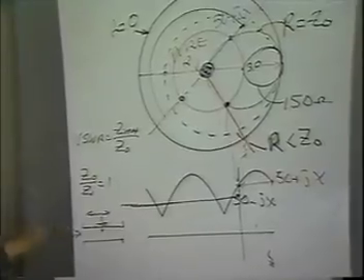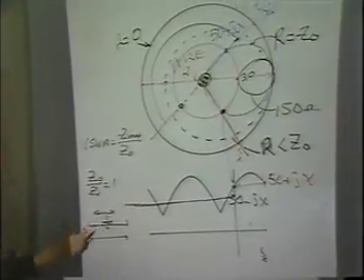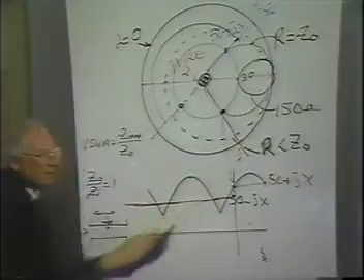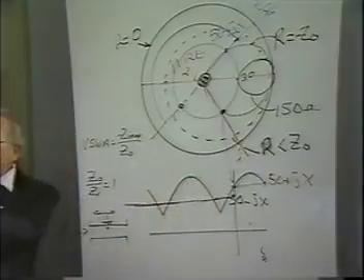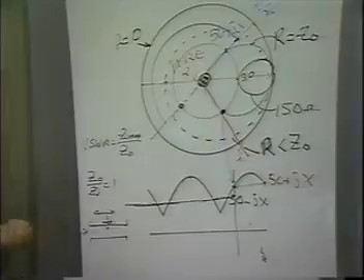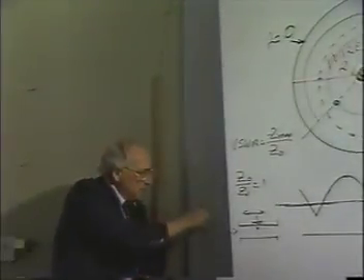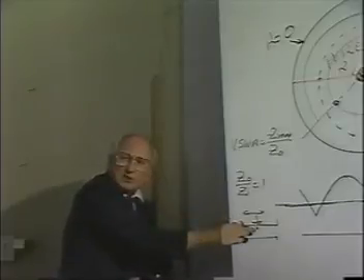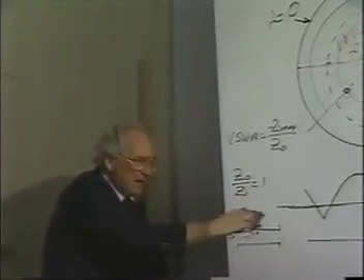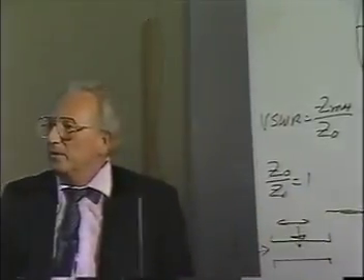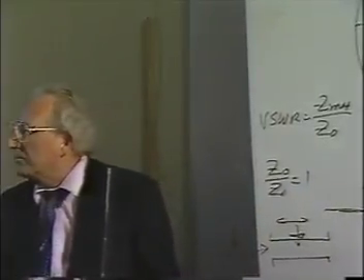I can move this probe back and forth, and I adjust this one until this is gone, and the only thing I see left is as I move the probe along the line, in what's called a slotted line. I move this probe back and forth, and I keep adjusting this probe depth and along the line until I see nothing except a straight line.